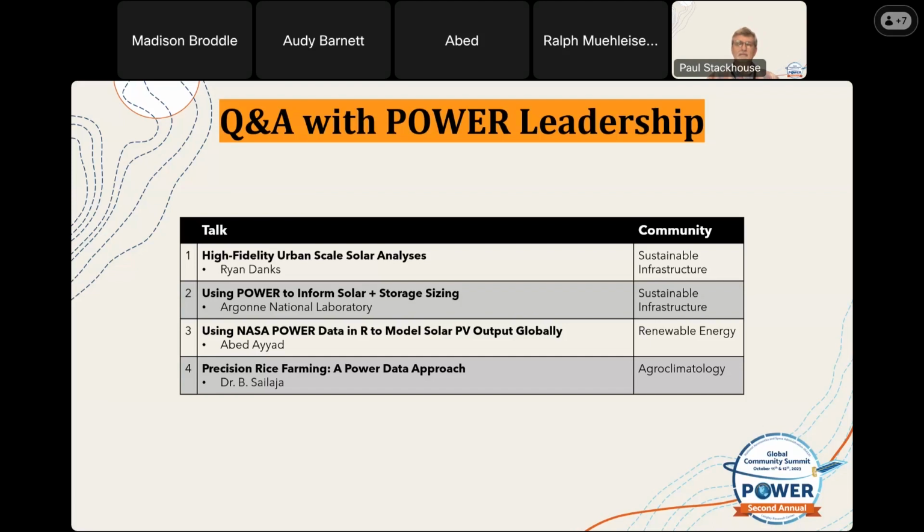If you're asking though, and you're worried about trying to do things as I am for backup power, and I'm worried about when it's really bad and cloudy out, it's a lot more sensitive to making sure you tilt for those winter months, because that's when, at least here in the north, you are going to have the worst output. So that one's a little bit more sensitive. So if you're looking at overall average power output for the year, it's fairly insensitive. But if you're doing it for backup and you need to make sure what your minimum production is going to be, it's a lot more sensitive.